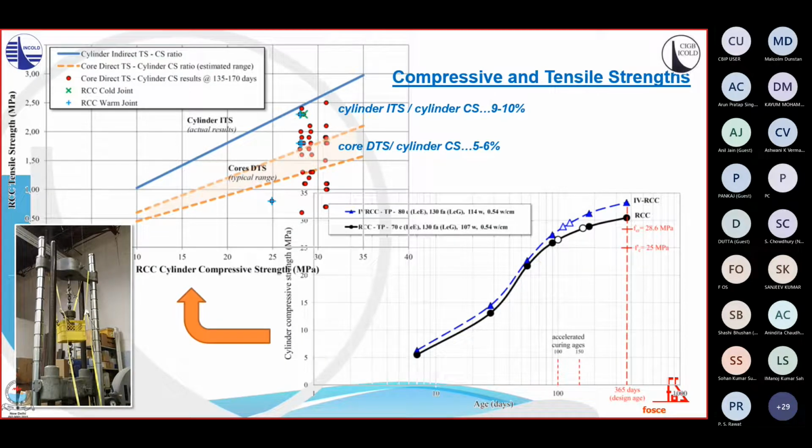On finalization of the site laboratory tests, ideally only a single mix should be selected to be used in the construction of the full-scale trial, FST. In order to be able to reach conclusions, the trial placement should not be used to redesign the mix, but simply to make minor modifications and optimizations to the laboratory mix if found to be necessary through real-scale observation.